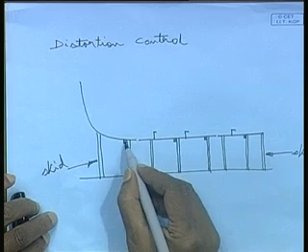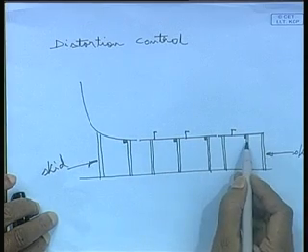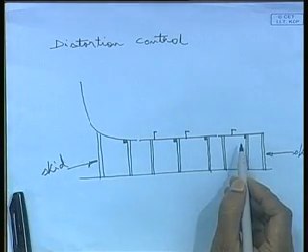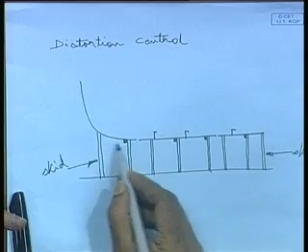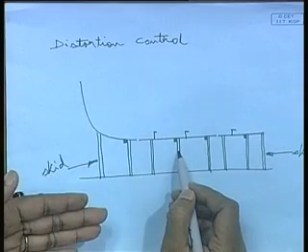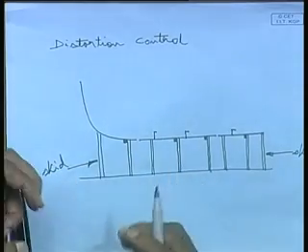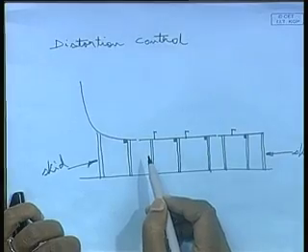These small squares I have drawn represent small lugs. What is a lug? A lug is nothing but a small piece of plate which is welded to the bottom shell or the shell plate, not necessarily bottom shell, it can be any structure being fabricated. So, to the shell plate and to the structure, that means they are restrained from movement.